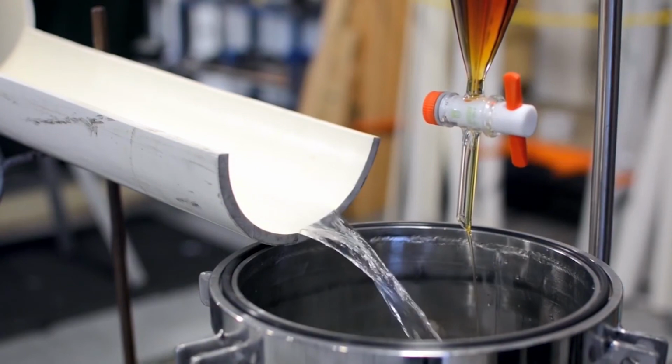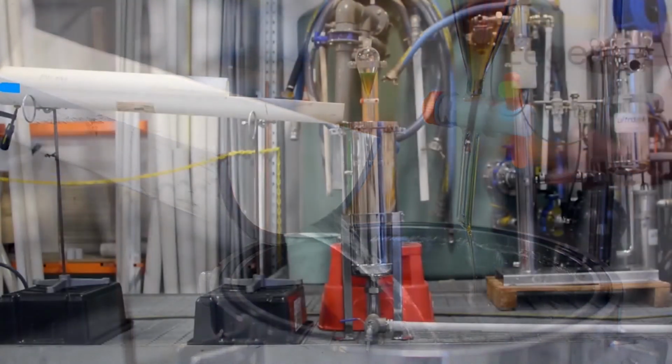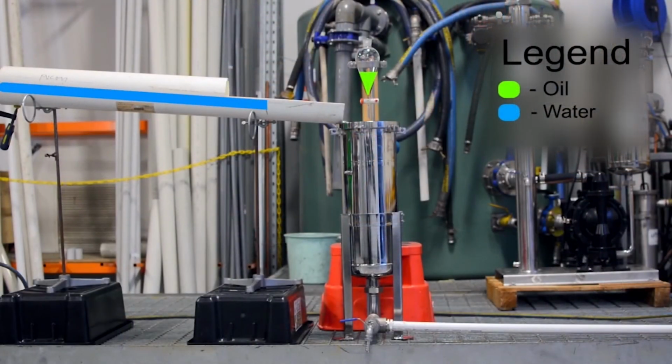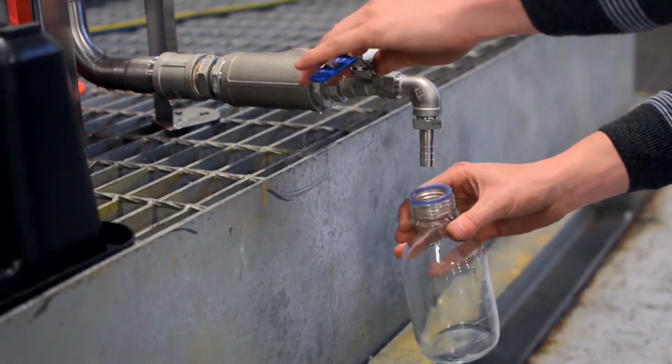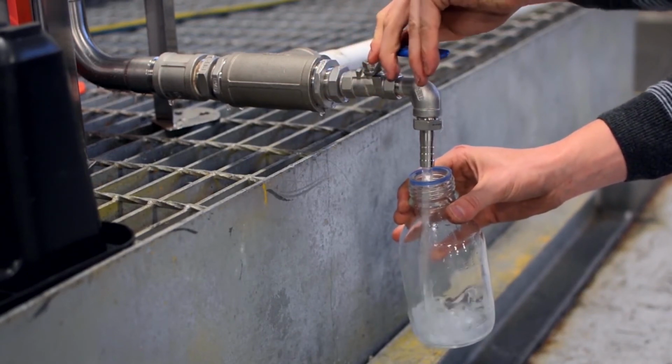It involves water trickling down a pipe with oil dripping into that mixture. Water is allowed to flow via gravity into the collecting chamber, where at the same time fuel oil is also allowed to drip into the collecting chamber. This produces the oily water, which is subsequently allowed to flow into the oily water separator via gravity, where treatment takes place. When the water is treated, a sample is taken and the efficiency of the oily water separator is